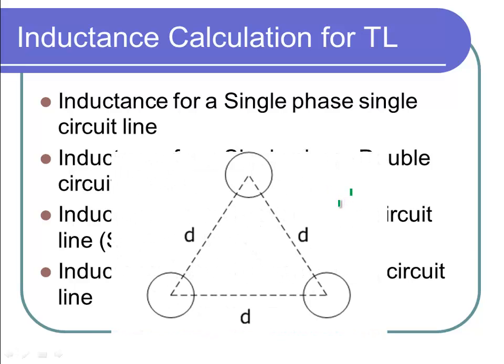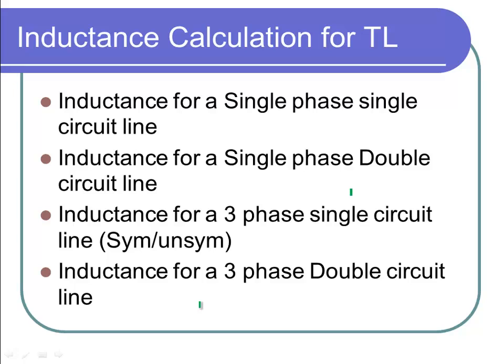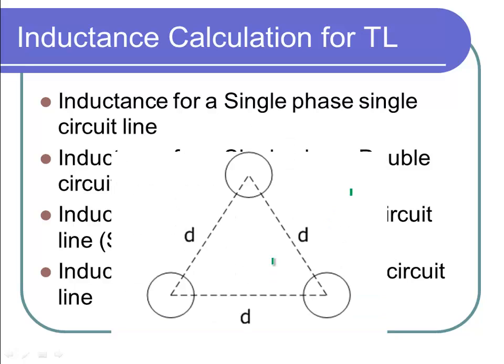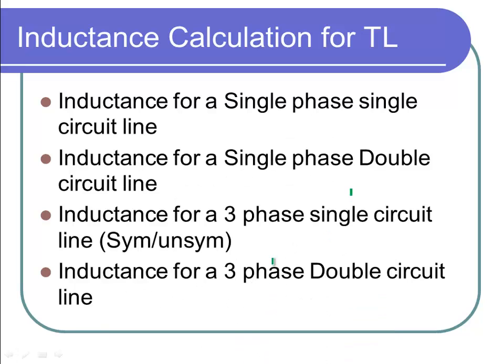The three-phase conductor is somewhat like an equilateral triangle. The distance among the conductors is the same on all the sides. Also, it's possible to make your three-phase single circuit in the form of uneven distance. So this one we are calling unsymmetrical spacing. If you see here, conductors 1, 2, 3 are not at the same distance, all are different. Why do we have to especially concentrate on these two? Yes, because of this distance your inductance may vary.